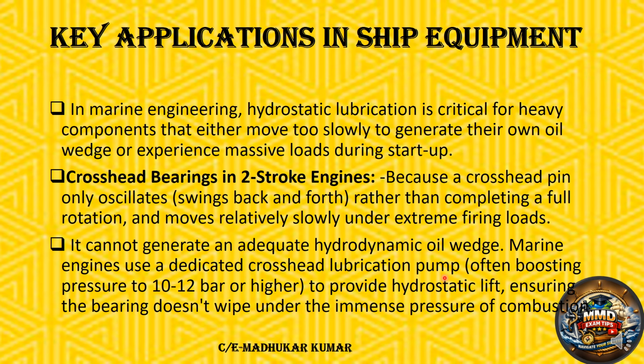But now, like in the WinGD engines and all, there is no dedicated crosshead pump. The same oil is going, and they are generating the lift. The lubrication in the case of Sulzer and WinGD will be discussed in another video. But just remember that the hydrostatic lubrication occurs over there.